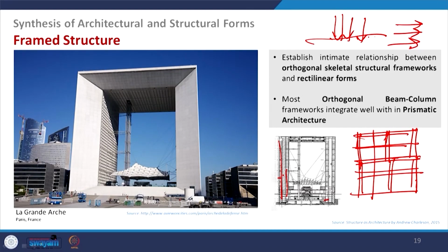The gravity load can be taken well care of by this, but when you go vertical, as we have seen in the load discussion, with the increase of height, wind pressure will also increase. So, there we have to support it with some other advanced techniques.